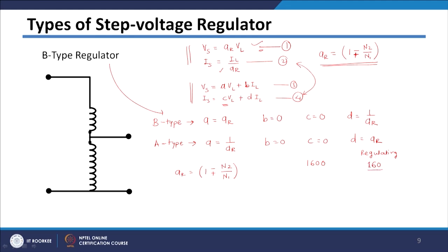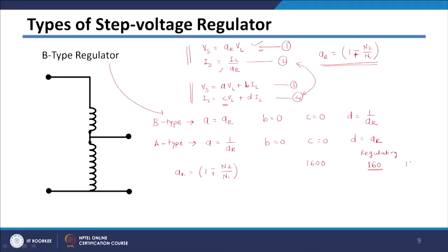And from these 160 regulating turns, we are taking 16 taps out. So there is plus 16 taps and minus 16 taps. We do our plus minus just by raising or lowering the switch, by selecting the switch. So there will be 16 taps we are taking out, so 16 variations will be available. Since we are taking 16 taps, per tap the number of turns will be 10 turns, because we are making 16 divisions. So per division or per tap there will be 10 turns.